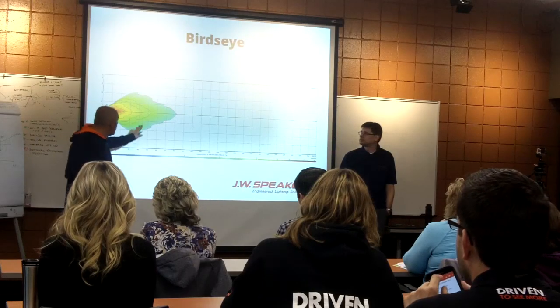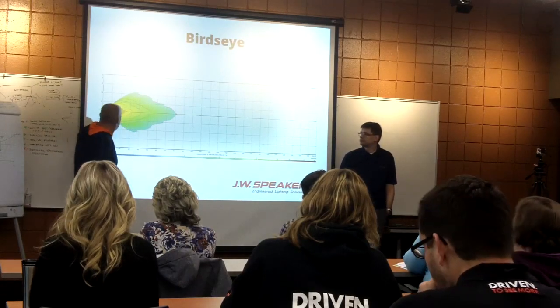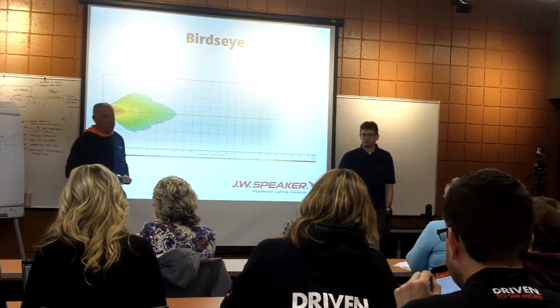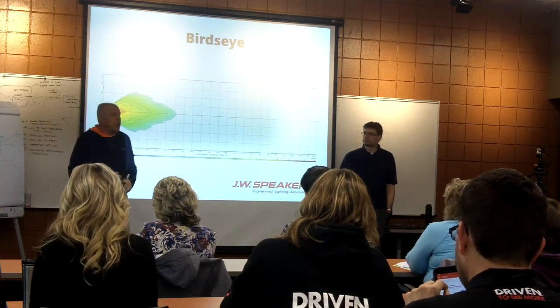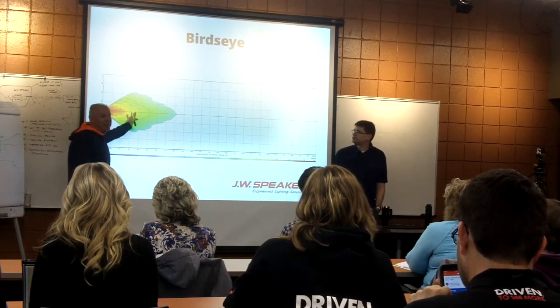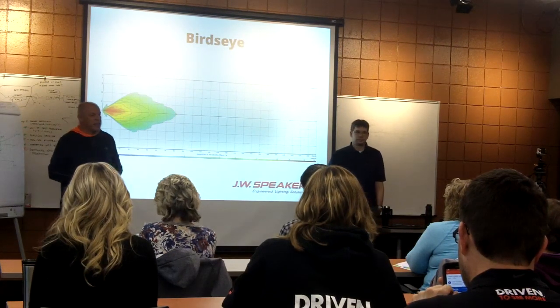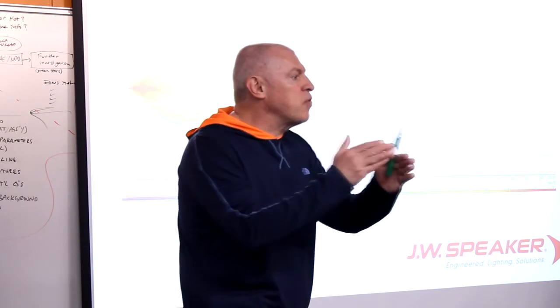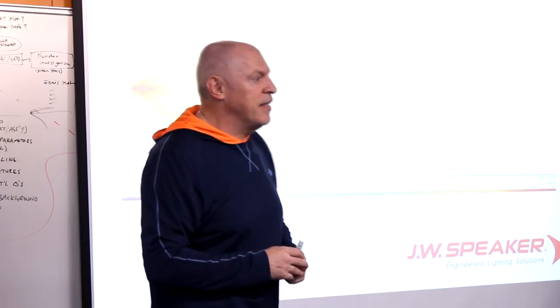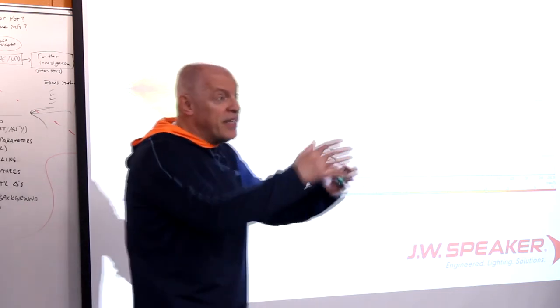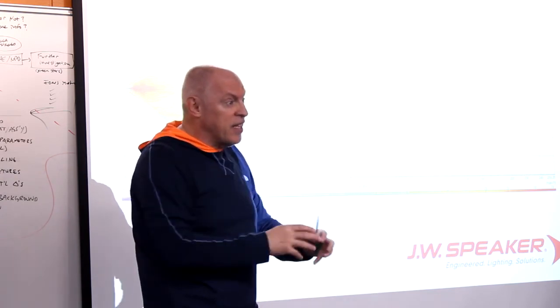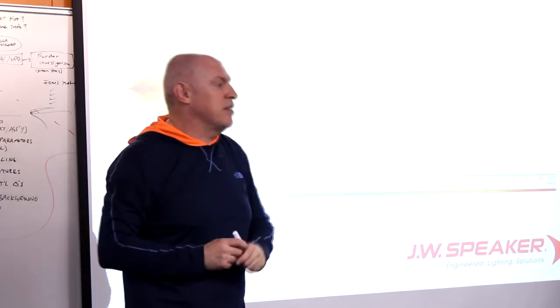So lux is the brightness of a surface by this source at that distance. And you cannot use candela in this case. It doesn't exist as such a unit. It's lumen per square meter. That's the lux. So they take some of those and make a derivative of that, which is the lux. Okay.